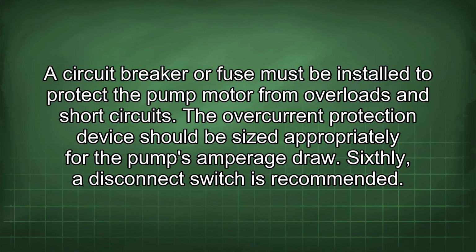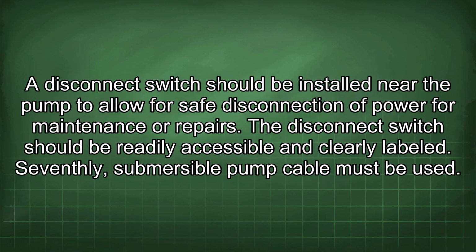Sixthly, a disconnect switch is recommended. A disconnect switch should be installed near the pump to allow for safe disconnection of power for maintenance or repairs. The disconnect switch should be readily accessible and clearly labeled.